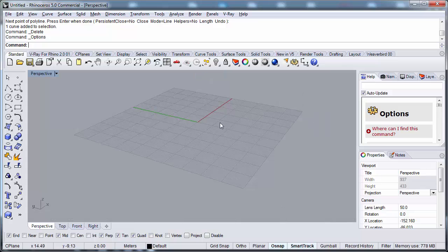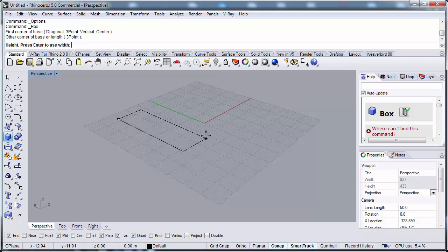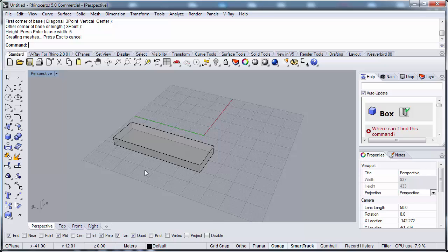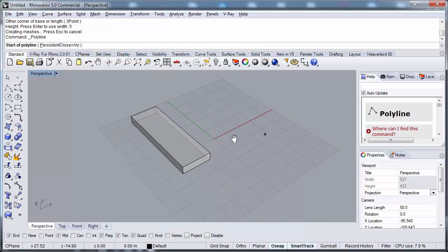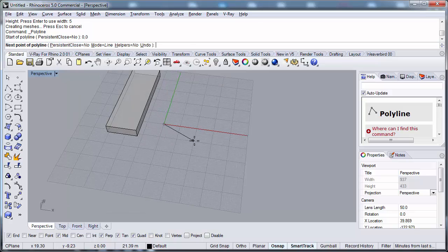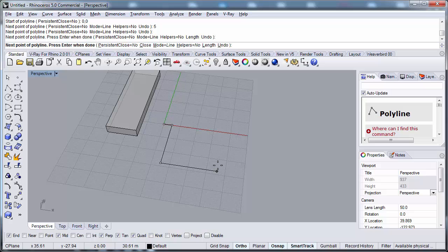Let's go to the perspective viewport and put some objects in. You see, whenever I go to create an object, the command line is active and asks for things. It asks for a height. I can write my height also. So I also have Cartesian coordinates. If I write 0,0, my line will start from the origin, 5, and with shift I can keep ortho temporarily.